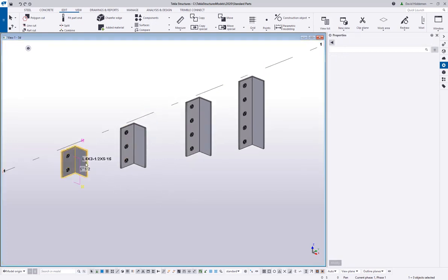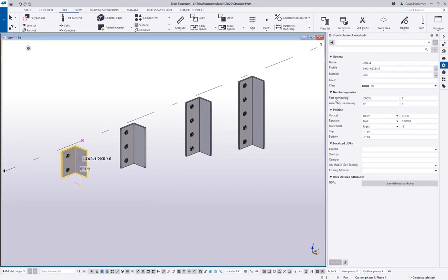After that, you want to make sure that you set these up with the part numbering prefix being what the desired standard part mark would be. Different companies have different methods for calling these out. For simplicity's sake, what I did was I went through and called these out as 2-row, 3-row, 4-row, and 5-row. So these could be anything, right? But you want to make sure that that mark, whatever you want it to be, is going to be in the part prefix of that object, okay?